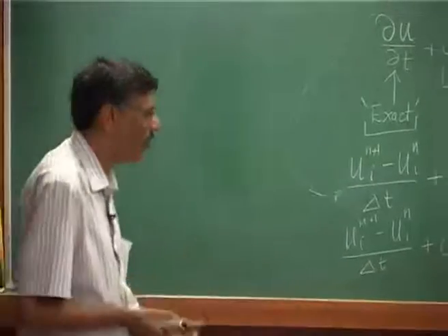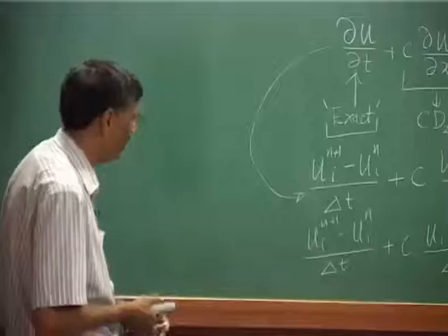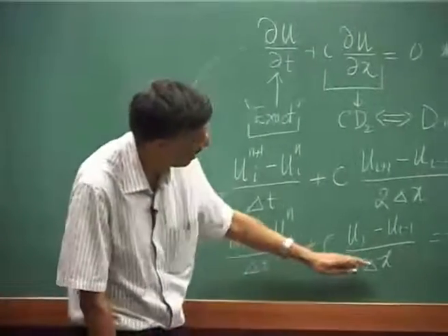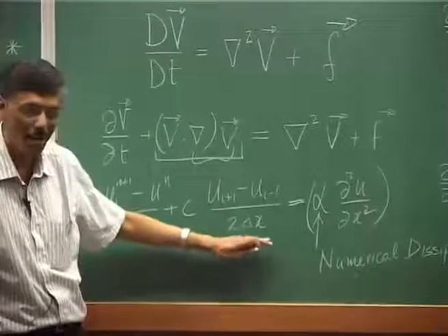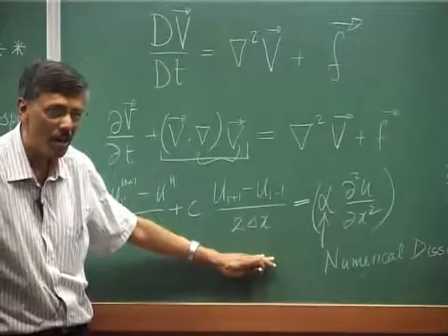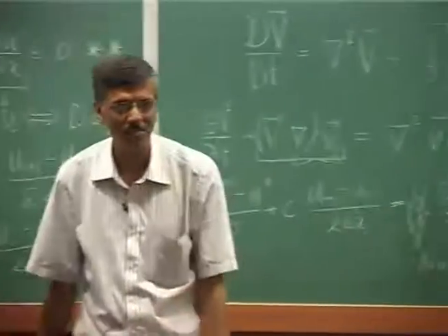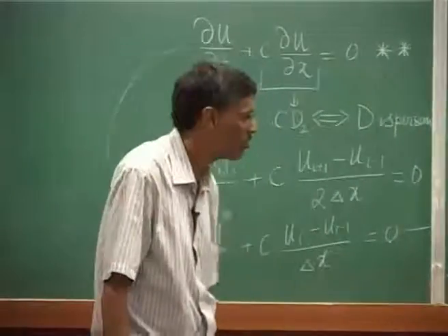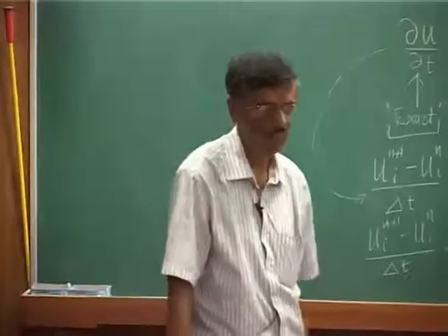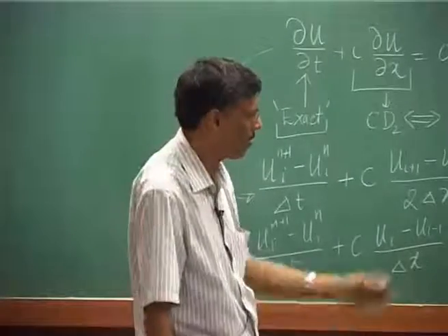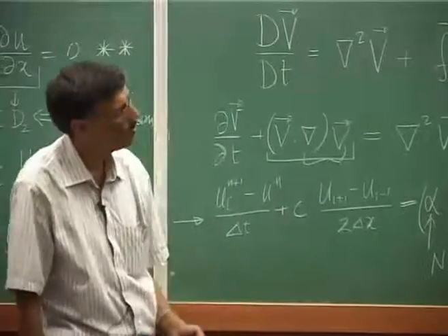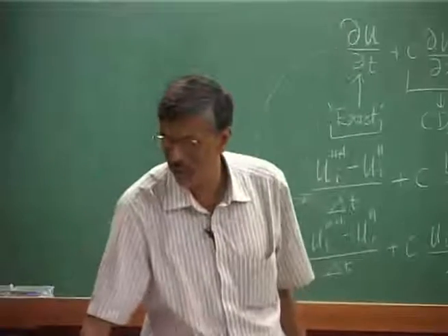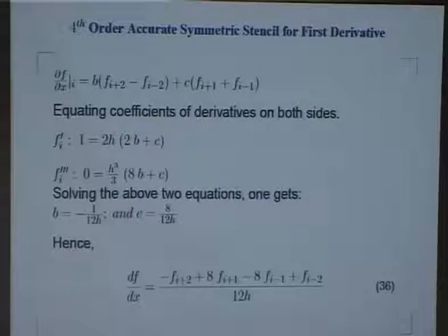And what is the way you do upwinding? You have seen that when I do first order upwinding like here, that is equivalent to discretizing the convection term by the second order plus a second derivative term. So, that is your first order upwinding. So, I can extend this logic. Suppose I do not write it by second order central difference scheme, but I want to do it with a fourth order term here.